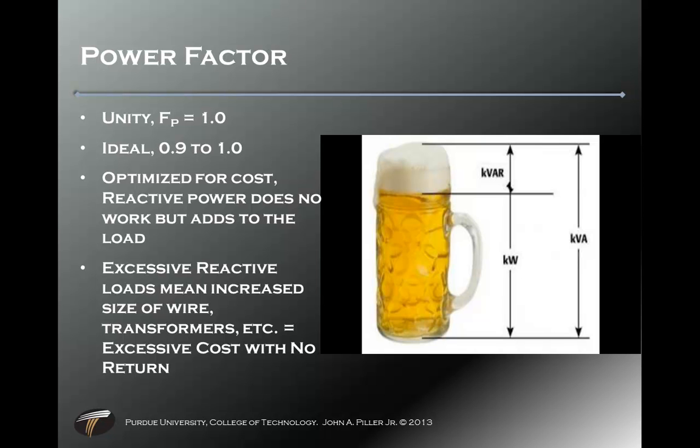It becomes 0.8, 0.7, 0.6, all the way down. If we have a very small reactive load, a small Q, be it positive 90 degrees or negative 90 degrees, we have a reduced angle, which increases our power factor. The cosine of 0 is 1. So angle 0 has a perfect unity power factor, which means S is completely equal to P. So P divided by S equals 1.